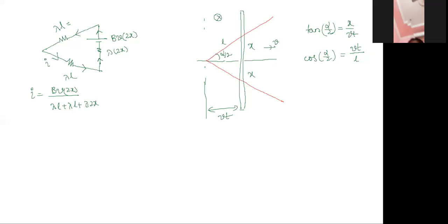From this onwards, we want to find the current in the circuit as a function of time. This is E, this is R. So there is a current of I2. This is L. Again the same story. At any instant, I is the current in the circuit. So E minus L di by dt minus IR equal to 0.